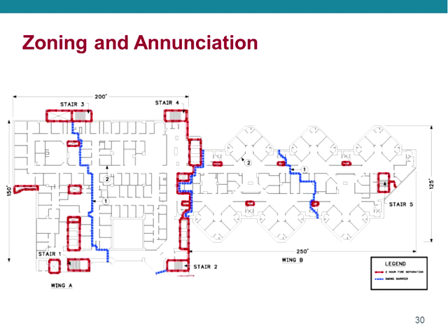So let's take a look at a floor plan to give you some idea of what we're talking about. I have a 2-hour barrier right over here, as indicated by red. So I really have Zone 1 and Zone 2, or maybe 1, 2, 3, and 4 zones here, because I have smoke barriers in other parts of the building. But typically, we would zone this as 2 zones, because I have a 2-hour barrier between this area here and this area here in this particular floor plan of this hospital.